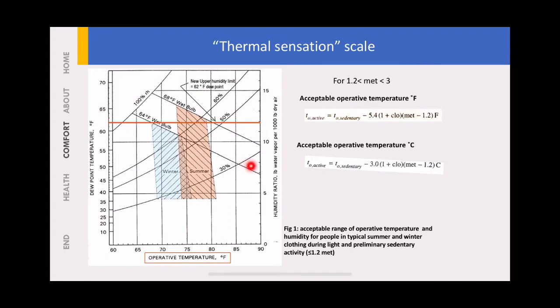If you go this way, it will be very hot. If you go to the left, it will be very cold. If you go to the high place, also the relative humidity will increase. If you go downwards, the relative humidity will decrease. Right? Having a relative humidity decrease means you are taxing your air conditioning system to suck out air from that space. That means more energy needed. The higher you go, the less energy is needed.